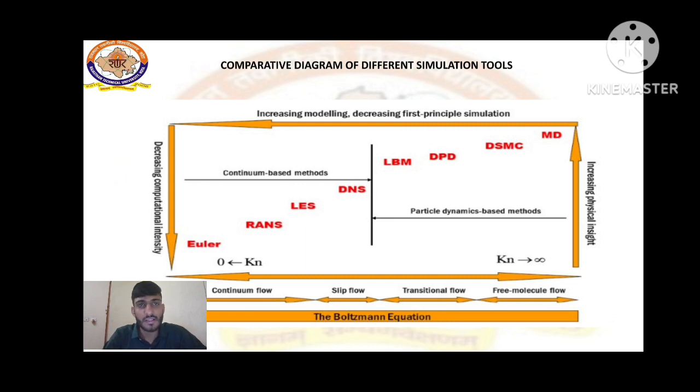So moving ahead with the disadvantages of the lattice Boltzmann method. First is the limited applicability. It can be applied to only a small range of phenomena, which leads to the second, limited scalability. In this, only certain types of problems, especially high viscous flow and low Reynolds numbers, can be simulated.